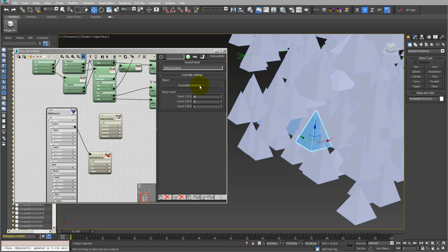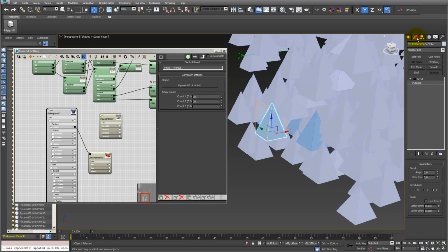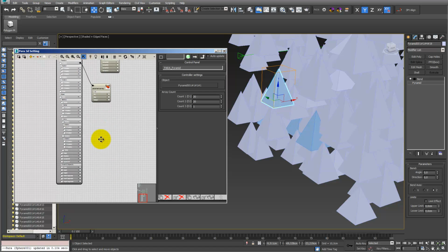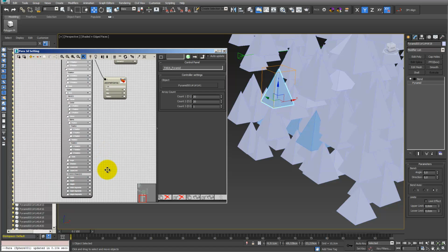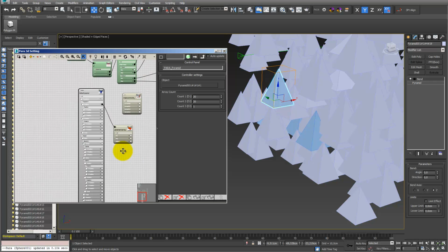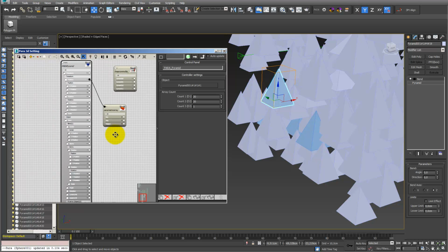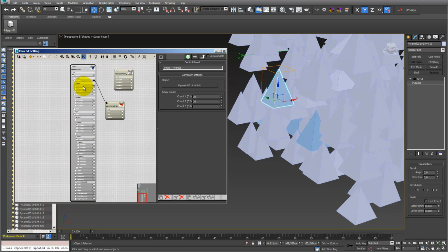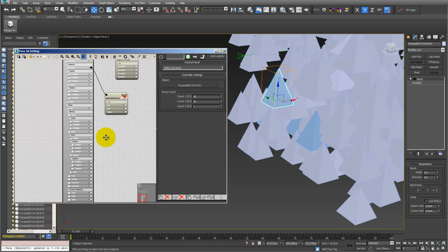So what you have to do is select your first member again, which I did right now, and then go into reload properties. After you did this, you can see that all your other objects also have this bend modifier. You can also see that this bend modifier is a part of your parametric container. With this, you can already see that your container is really long. Just imagine you add some edit polys and it's a really long container. So this tool of show all channels or hide unused channels becomes really important.